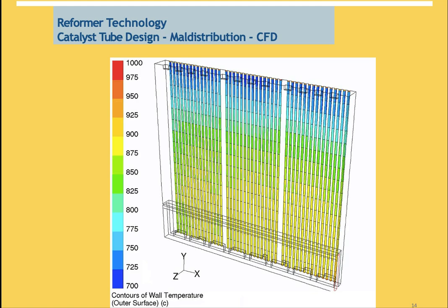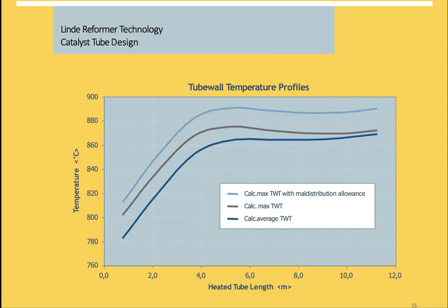Okay, and the corrective action related to this criteria is to increase the furnace firing, reduce the feed rate, check the catalyst aging and activity, verify the shift converter by sending a sample to the lab, and adjust the pressure if possible. You can do something like that. Okay, so this is the gradient related to the tube behavior.